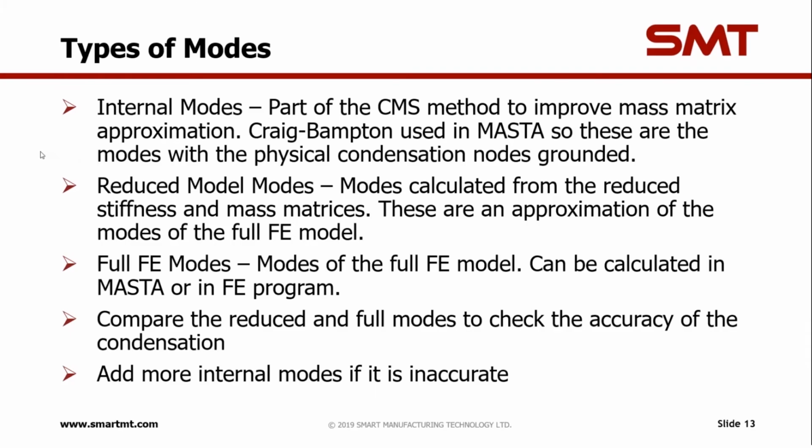So the final section for today is just to explain the different types of modes that we report in the FE mode in MASTA. I'll show these in the interface in a second as well. The first of these is the internal modes. These are part of the CMS method in order to improve the approximation of the reduced mass matrix.